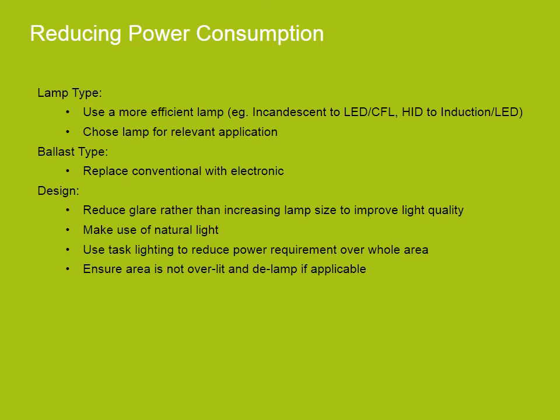Irrespective of whether you are designing a lobby for a 6-star hotel, an office, or an industrial facility, lighting design must take a holistic approach that not only provides efficient illumination, but creates a comfortable, stimulating, and interesting environment. Simply achieving the required illuminance does not guarantee a satisfactory lighting installation, and over-illumination will not necessarily act as a safety margin. Other aspects of the visual environment such as glare, contrast, and user satisfaction will have a greater impact on whether a lighting installation is perceived to be successful.